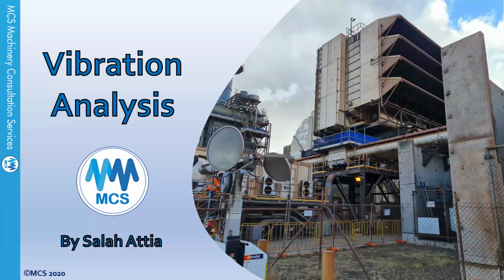Because the high frequency range is easily excited by any frequency generated by the bearing. Bearing faults have a very low amplitude and a very high frequency. That's why we use what we call HFD, or high frequency detection techniques. You have a very quick, very high frequency event with very low vibration. Normally the high range is excited by any frequency.